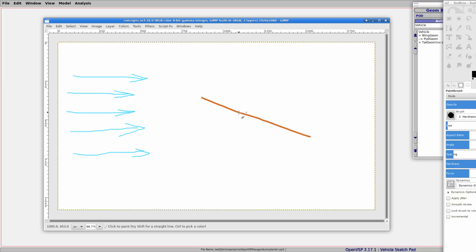Anyway, so as a result of this airflow and the angle, we would get a drag. We would also get some sort of a component of lift as well. Yeah, I know. You've seen this 1,000 times. Just bear with me. Now, the magnitude of these in the real world, we would measure this in pounds or kilograms or newtons or something like that. But it's not the exact number of newtons or kilograms that we really want to consider, because that will depend on how fast the wind is flowing and how large this wing is. What we really want to check is the ratio of lift to drag, because that will determine at any wind speed and any size how efficient this thing is.